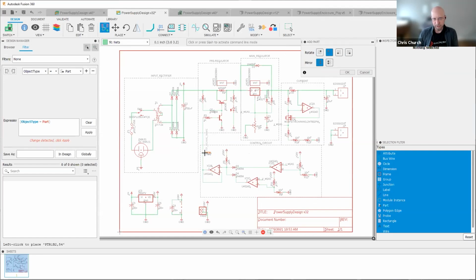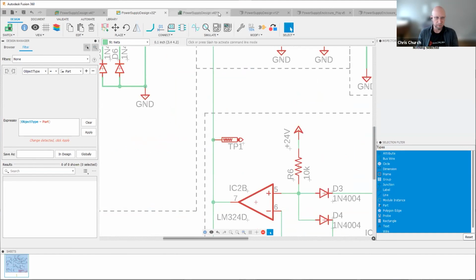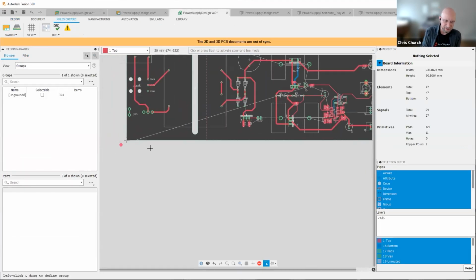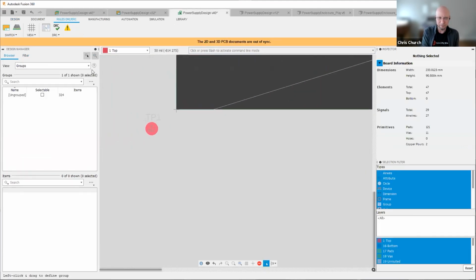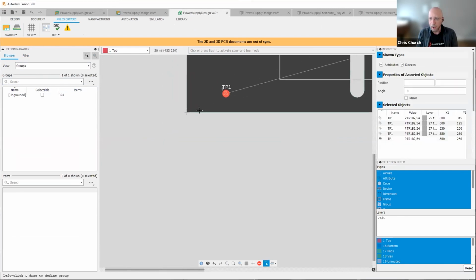But typical labor rates, if we're thinking US, run around $1 a minute at different factories. So for every minute of test, you're adding $1 to the device cost. So if we can work with you and build a test fixture for $15,000, does it save 15,000 minutes over the course of your production? That's really what we're going to be looking at there, the life cycle of the product, how much time we're saving, et cetera.